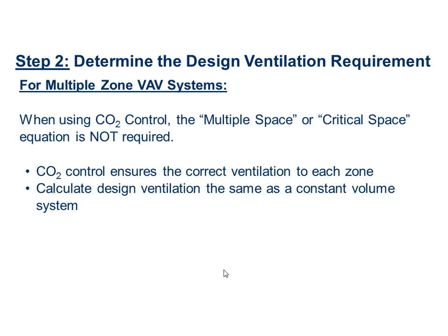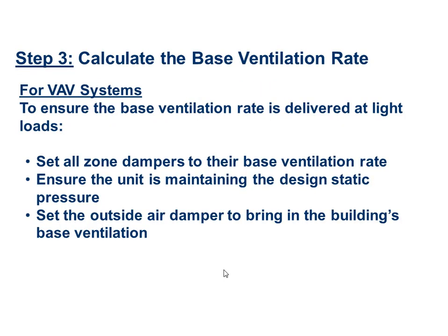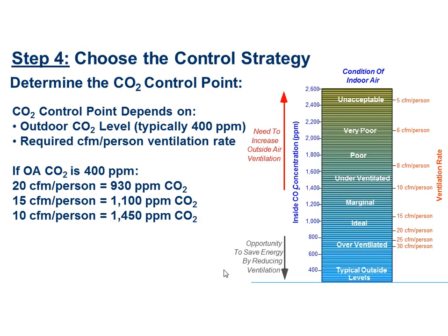So in the interest of time, we're going to jump to a couple more detailed things here. This chart on the right gives you an idea of what some normal CO2 levels might be and what ventilation rates they correlate to. If you remember that ASHRAE formula I showed you, these two are directly linked. The whole reason we came up with the 10, 15, 20 CFM per person numbers was based on backing the CO2 levels out of that formula.